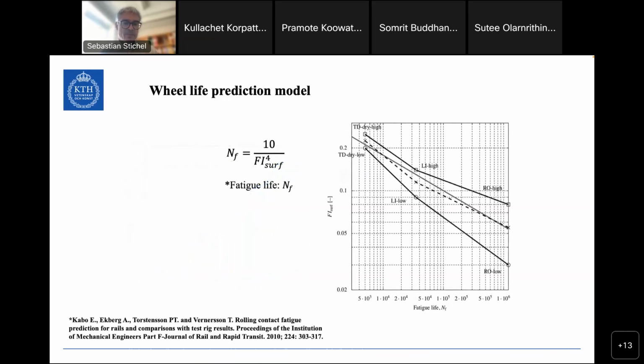And here are some laboratory measurements that colleagues from Chalmers University have done, which helped us to calibrate our model with the Wöhler curves they have measured in the laboratory. We could calibrate our model to say after how many exceedances of the shear stress limit we have a failure. And by that, you are able to make not only qualitative but also quantitative assessments.